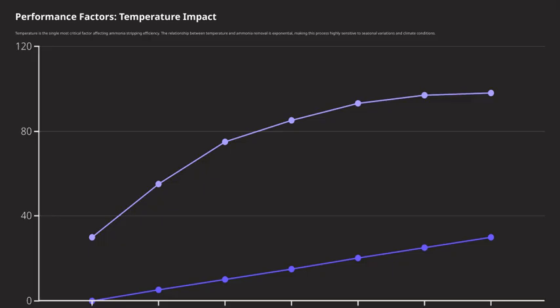But it's not just about performance. Cold weather introduces several operational challenges. Icing can form on tower packing and structural parts, which might even cause structural failure. Fogging from the exhaust air can impair visibility on nearby roads, creating safety hazards.